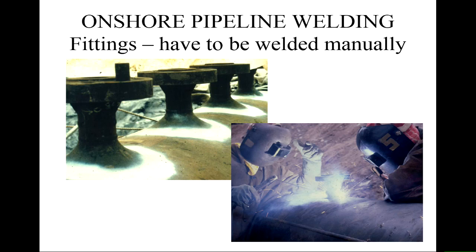And this is a couple of welders working together on a small piece. Sometimes if you weld on a fitting on one side, the thermal contraction stresses would pull the part one way. And so if you weld on both sides at the same time, stresses are trying to pull it one way and pull it back the other way, and it keeps it in the centre. So if you balance the welding around the fitting, so people welding at the same rate on the opposite sides, then you often find you get better properties, no distortion, no changes in shape.